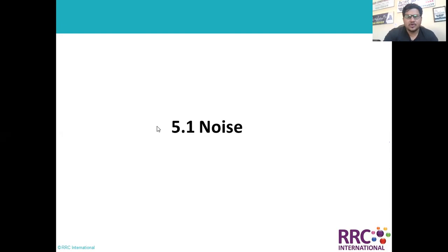Once he noted down the noise levels, somewhere it was above 105 decibel, somewhere he noted 90 decibel, while the legal limit is 85 decibel, and for the UK it is 80 decibel. And he just prepared the report for each rig and shared it on the same day.